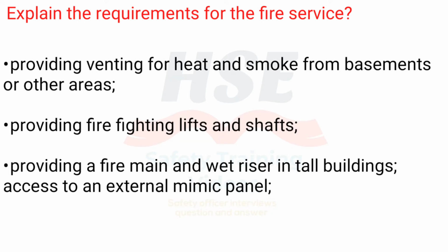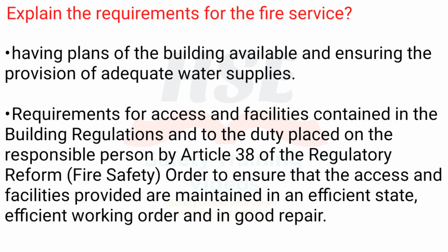Providing venting for heat and smoke from basements or other areas. Providing firefighting lifts and shafts. Providing a fire main and wet riser in tall buildings, and access to an external mimic panel. Having plans of the building available and ensuring the provision of adequate water supplies.